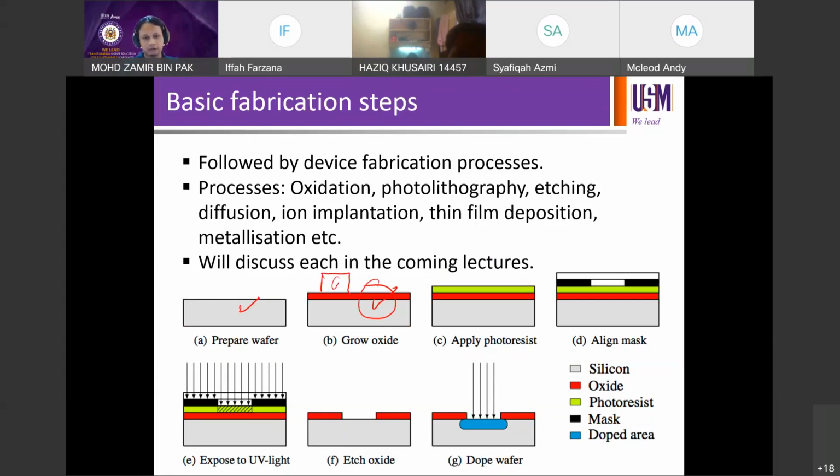You're going to have the gate here, and then eventually you're going to have source and drain here, but we're going to do something else after that in order to get to that structure. But this oxide for this particular step is for the gate ox, right? Gate oxide, below the gate. Then you apply a photoresist. Photoresist is a sensitive polymer compound. It's a compound that we spin coat. We cover this green area.